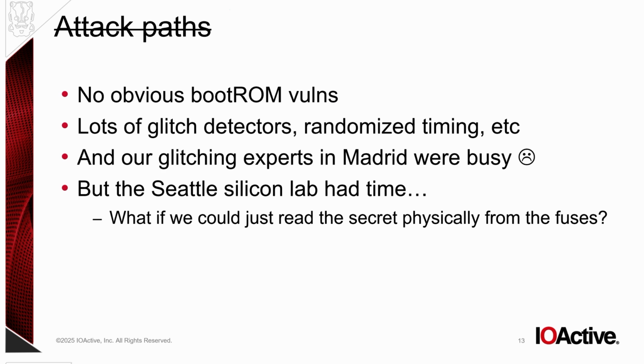It even gives us a nice cross-section of what this fuse or anti-fuse cell would look like, which will be interesting later on. So as I said, you start off with basically a 0, and then when it's written, you supply a high current to this area, and you make a 1 from it. So a fuse or an anti-fuse is a good way to write data into a chip after it's been fabbed.